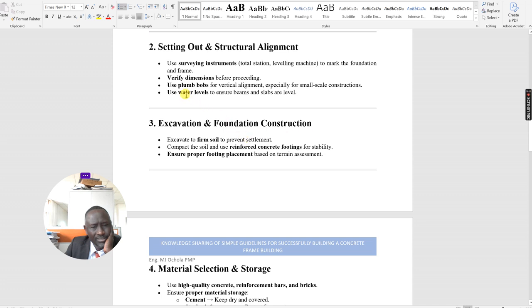In your model, you are designing a level floor, but during construction, if you don't maintain that and you allow some slope, then definitely you're going to create eccentric load behavior on your columns. That is how the cumulative effect arises: if the floors exceed about 4, 5 or 6 levels, you're going to find that when you're trying to build and plumb your block walls at the upper floors, you see them falling down, because the building is already out of plumb. So every level you achieve, you need to make sure you control the vertical levels and also the horizontal level.